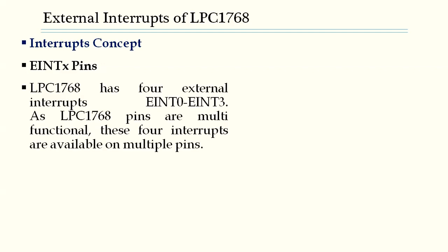The LPC1768, as said, has four external interrupts, named EINT0, EINT1, EINT2 and EINT3. The pins are multifunctional, and hence these four interrupts are available on multiple pins.